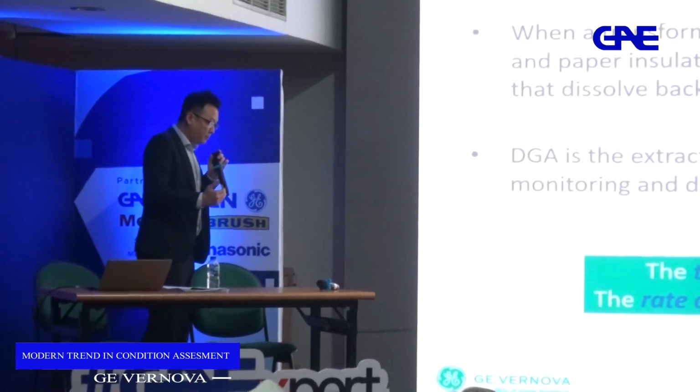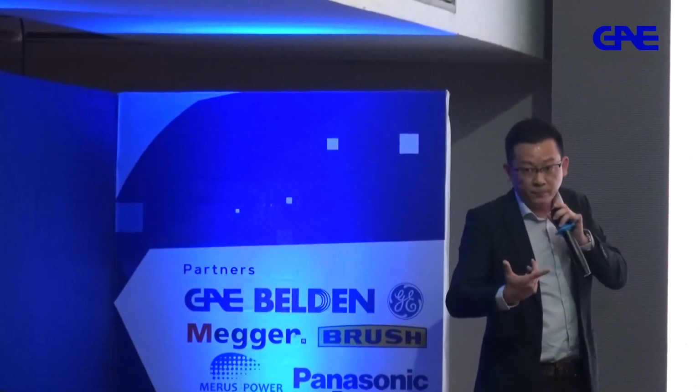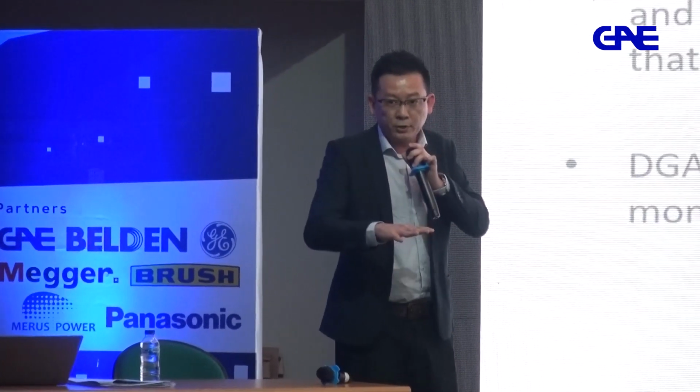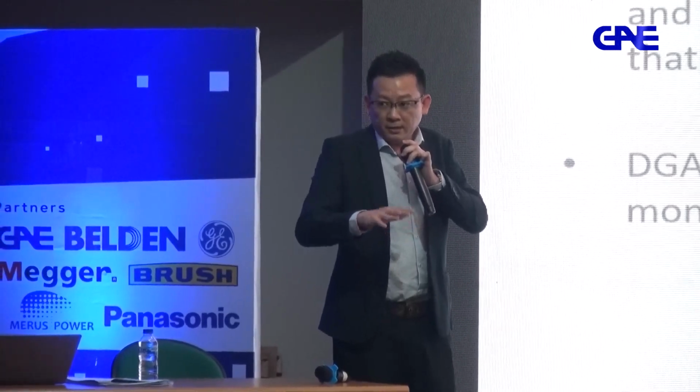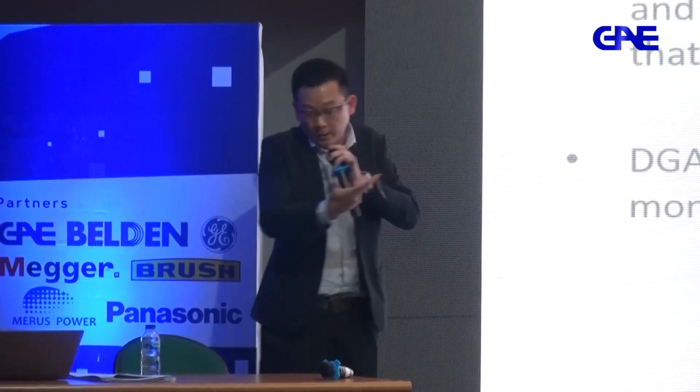Excessive temperature rise is probably due to insufficient cooling. When it comes to a power transformer, if you have an idea of the power transformer itself, there's always a cooling fan, a cooling group. So when the oil itself gets too hot, the fan cuts in and brings down the temperature of the oil. This will improve the insulation of the transformer.